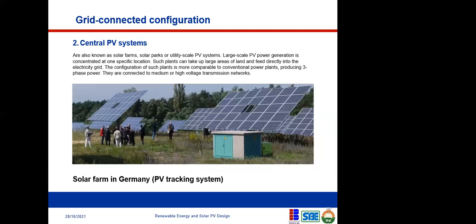So the service provider may need to carry out maintenance at a certain section of the grid, and they will request an outage on the grid. When they request an outage, your inverter should be able to know that there is an outage on that grid, and it should not send power to that grid. Otherwise, you induce power into the grid, which is wrong. It can cause damage and a health and safety problem. So there is more technical involvement in all of this, but I just want us to understand this.